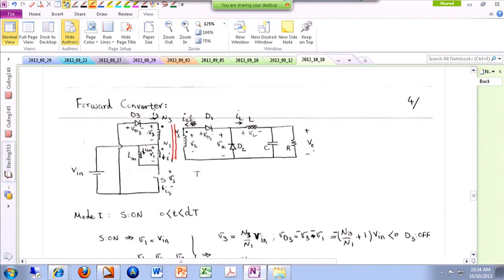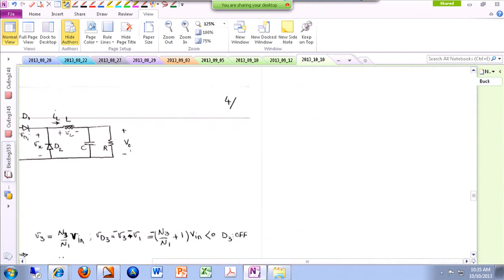So there is a transformer, and this transformer has 3 windings. Okay. So let me make these figures a little larger. We have this, let's say, magnetic core, and then we have this number 1 winding, and I place the dot over here, so immediately I have to follow this voltage polarity and this direction for this current.